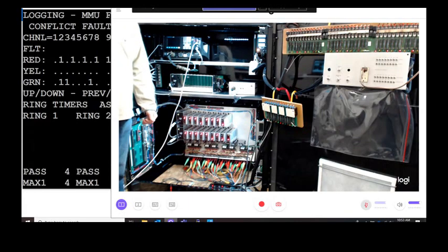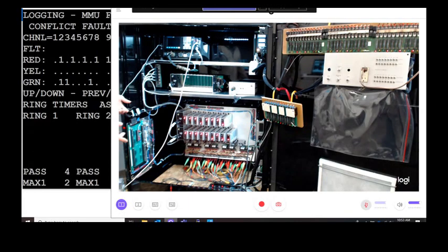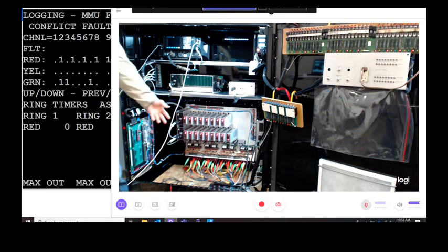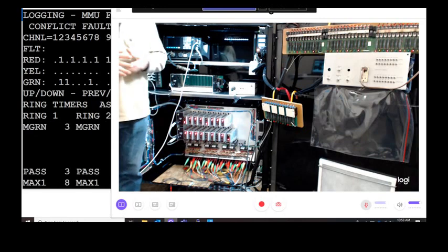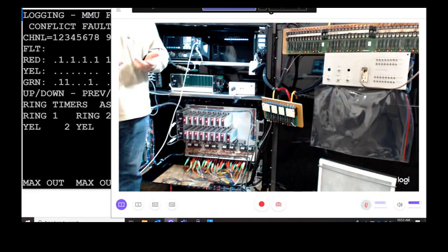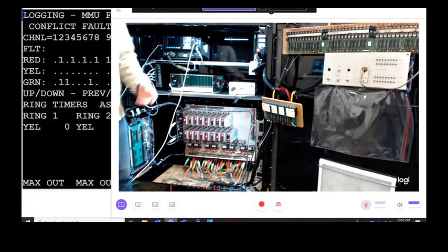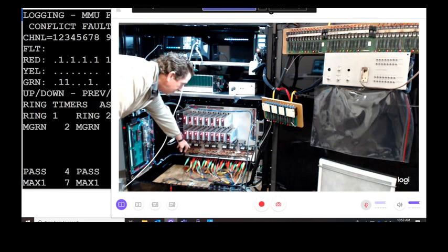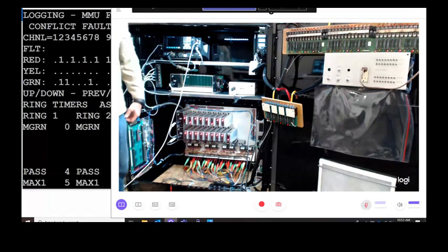And the one last way to confirm that, and I didn't bring one with me, is dummy lamps. I always say the last thing a contractor should carry with them are dummy lamps. Basically a receptacle that has an incandescent lamp in it. We can take that lamp and tie that lamp load onto 2 green and then over to the ground bar.